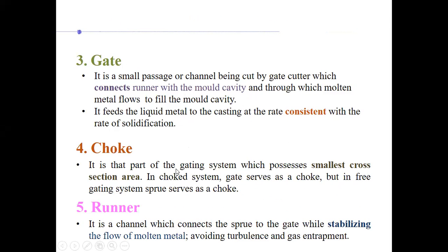And choke, it is that part of the gating system which possesses the smallest cross section area. In a choke system, the gate serves as a choke, but in a free gating system, the sprue serves as a choke. Okay, it depends. If it is a choke system, then your gate serves as a choke, isn't it? As you can see,